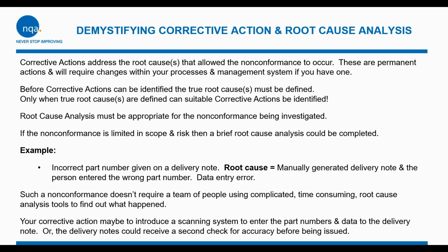Root cause analysis must be appropriate to the non-conformance that's being investigated. If the non-conformance is limited in scope, then a brief root cause analysis could be completed. An example would be an incorrect part number is given on a delivery note. The root cause can be as simple as they manually generated delivery notes and the person entered the wrong part number. It was a data entry error. Such a non-conformance doesn't require teams of people and lots of time and money to be spent. But your corrective actions should address the root cause, which is manual data entry.